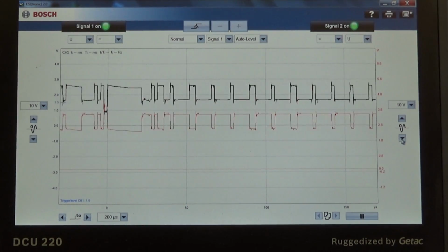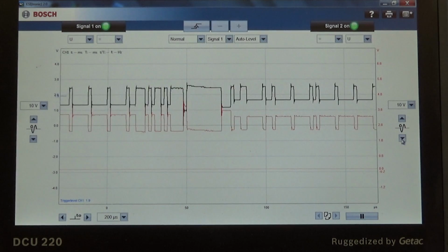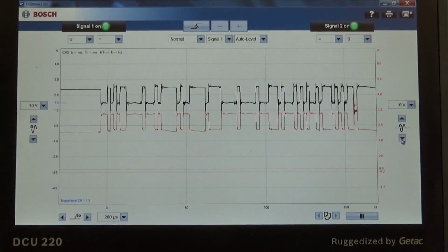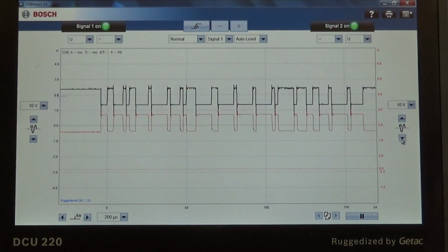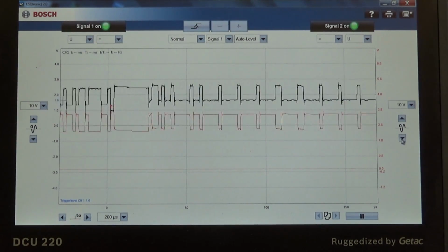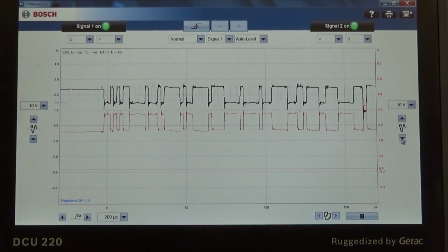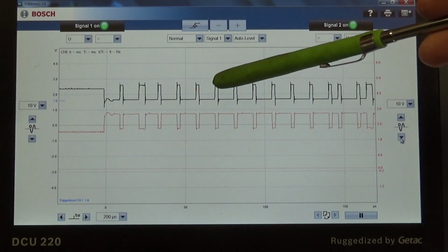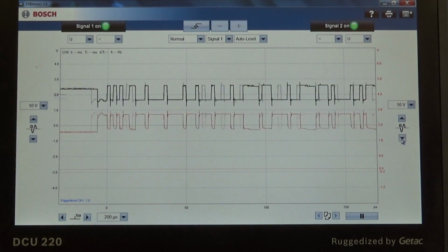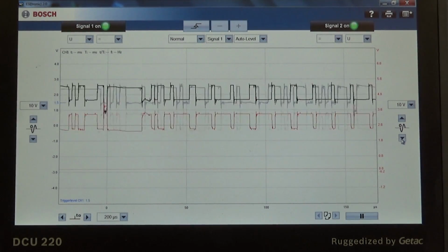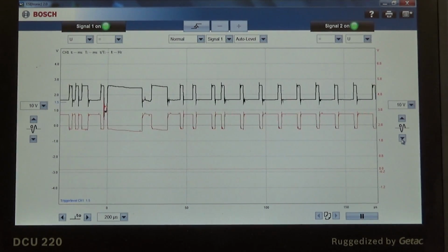Power off, 60 ohms between 6 and 14. You can do the measurements with the DVOM on 6 and 14 with the power on. You look at it, about a half a volt difference in the wires, and if you've got one of your terminating resistors out of the picture, it'll measure 120 ohms. Your two signals should mirror each other, nice square patterns that mirror each other, no big dropouts or anything like that. And like I say, they are fault tolerant networks, so they can be shorted to positive, shorted to ground, shorted to each other, and the minute you restore the actual physical layer, it returns.